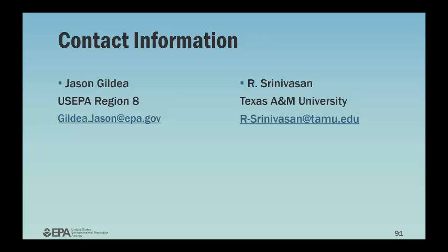Okay, you can change. Already we provide you 3 different weather data sources. For example, we give you the NCDC, the National Climatic Data Center, the NOAA National Weather Service data set. We also provide the PRISM data set, the gridded data set, and NEXRAD. So we are providing 3 different weather inputs that you can choose from. You can also choose the current land use. Then you will also be able to input your own land use change. Let's say you have done some analysis for your watershed, and you know land use X is going to change to Y at this percentage on this day of the year or this time period. You will be able to input that in the model.